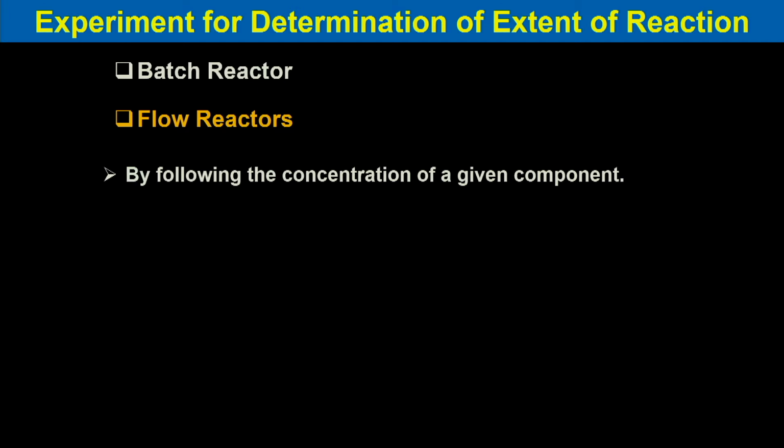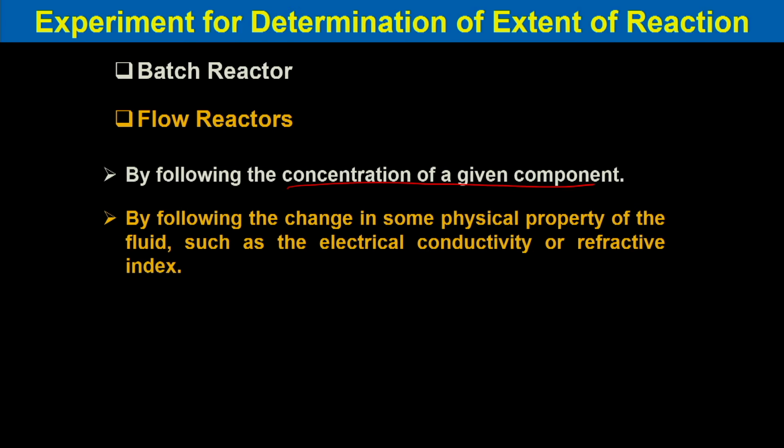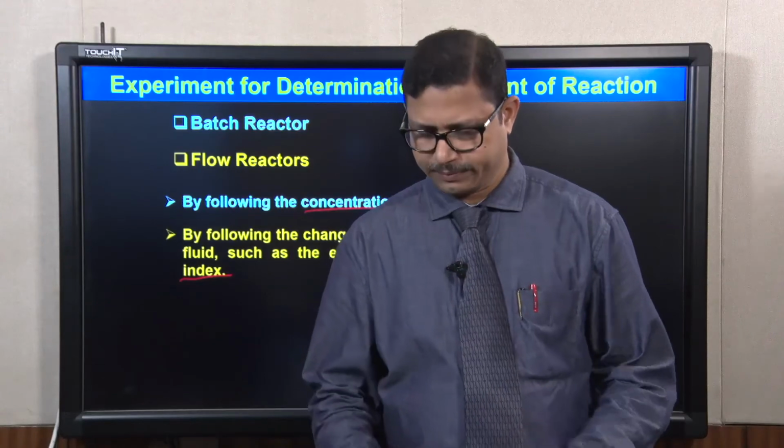We can do it by following the concentration of a given component. So, in a particular reactor, we can see the change of concentration for a given component, or we can follow the change of some physical properties of the fluid or of the reactants, physical properties like electrical conductivity or refractive index. The change of these properties we can follow in a particular reactor.